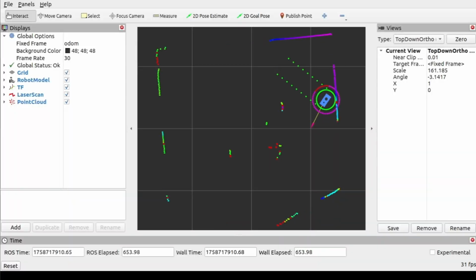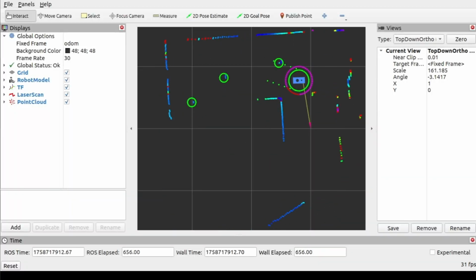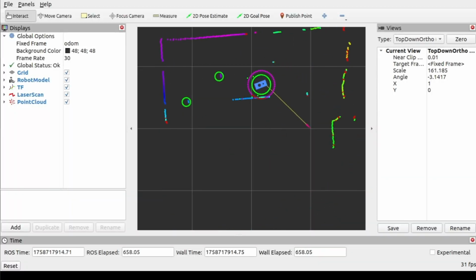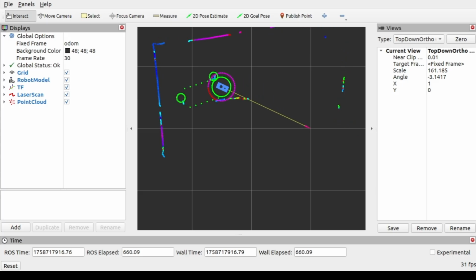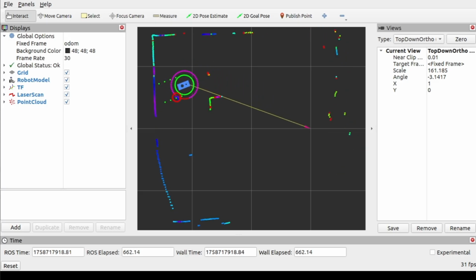A very interesting thing in our robot is that we are calculating its real-time position in the track. We are fusing the encoder value and the IMU value together, and thus we can determine the exact position of our robot in the track with centimeter accuracy, which really helps us with parking, obstacle avoidance, and lap count.